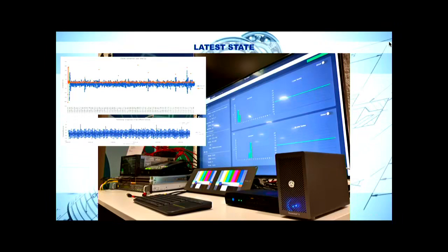So to be sure that we have good results, we also looked at the jitter of the clock and the resynchronization of PTP4L, how that worked out. And then we did a capture with those official high-grade boxes and with our cheap man's box. And it seems that we're pretty close to all the other captures. So I can say really confident that our live implementation is as precise as possible.